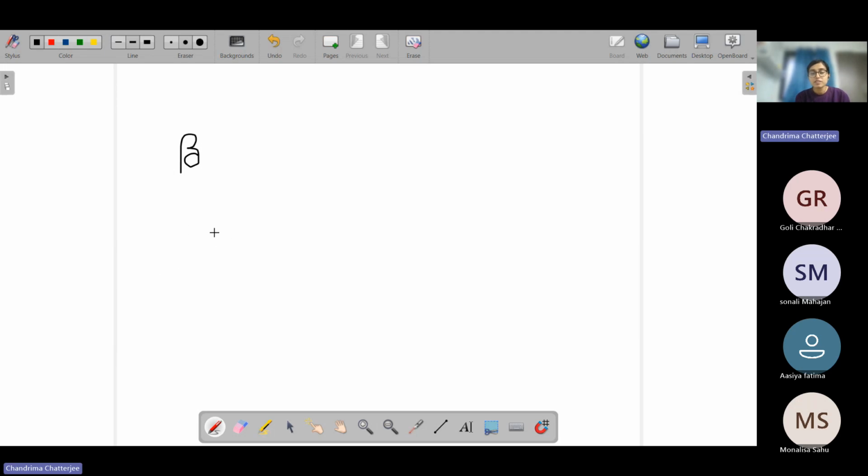Now they have already mentioned the line is lossless. So if we find out beta, beta is the square root of X and B, which we discussed in the last tutorial session. X is the inductive reactance, and B is the capacitive reactance.